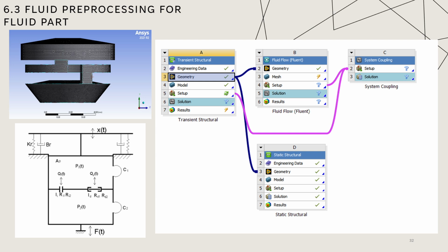For the high frequency condition, the decoupler is going to work more effectively, and I will cover the inertia track and only let the fluid go through the decoupler.